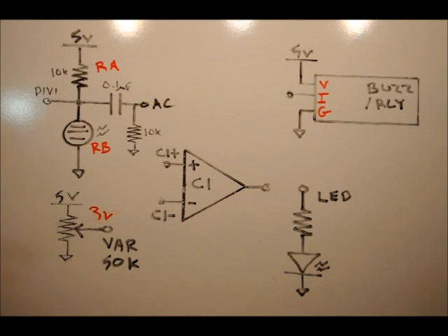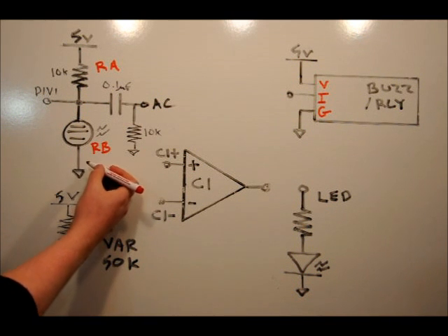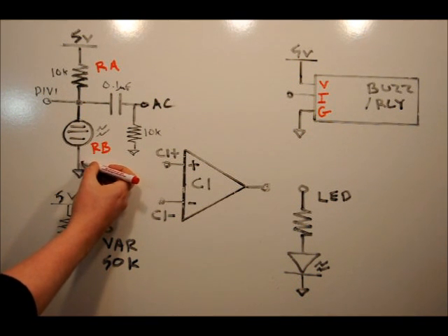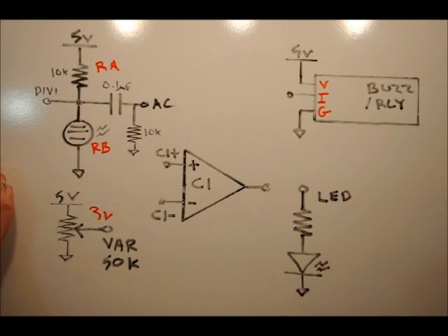Now, you can easily measure the voltage on VDiv by connecting your multimeter negative lead to the ground line on the power supply pin block and your positive probe, red probe, to the div1 line on the main pin block. And what you can do with that is you can essentially look around to see how the resistance changes based on how much light is hitting the sensor. And we will actually do that in just a minute.